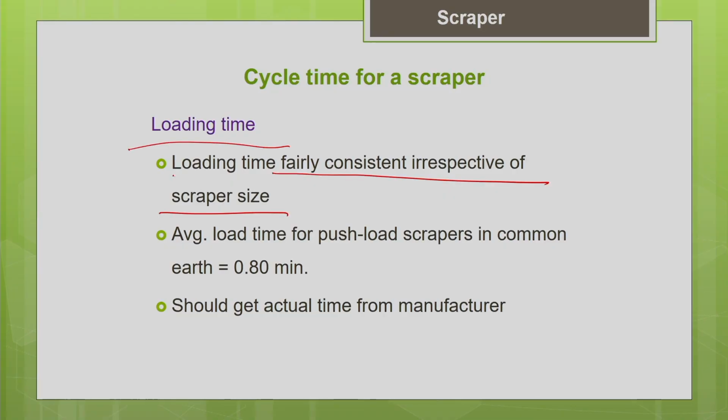According to the size of the scraper, you have to select the compatible size of the pusher, and we are going to supplement the loading power. That is why the loading time is fairly consistent irrespective of the scraper size. Since it is assisted with the pusher, the loading time won't change much.